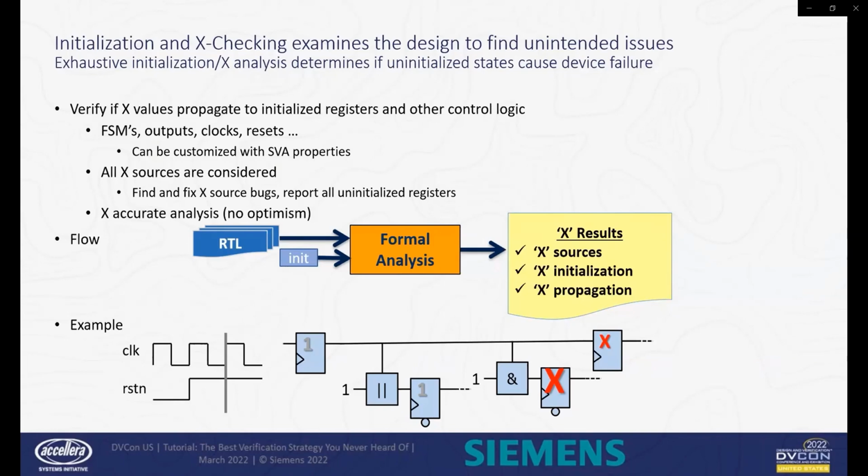This points to random behavior that would happen in silicon. Steps would need to be taken to prevent this X corruption from happening, either initializing the upper left register or improving the blocking logic for the lower right register are two possible options. X verification is a vital step to ensure that the design in silicon behaves as intended.